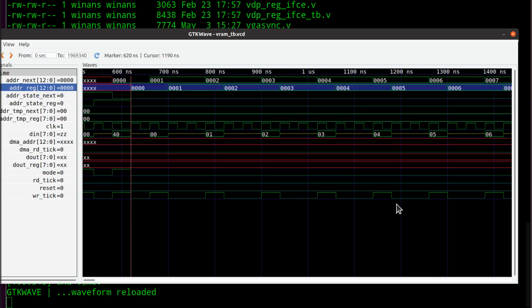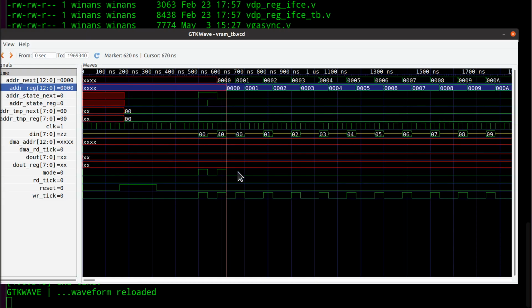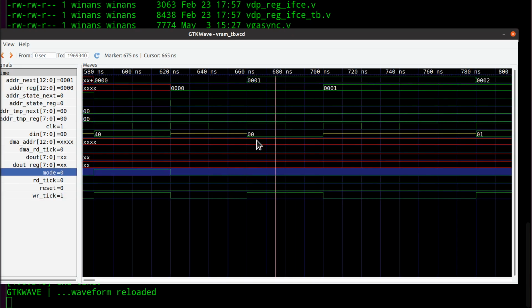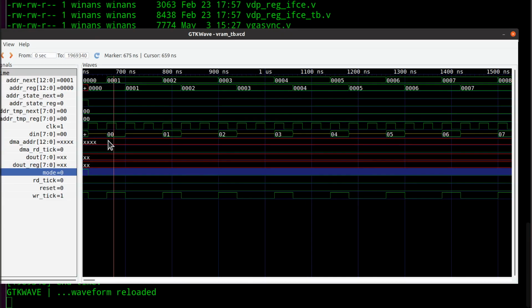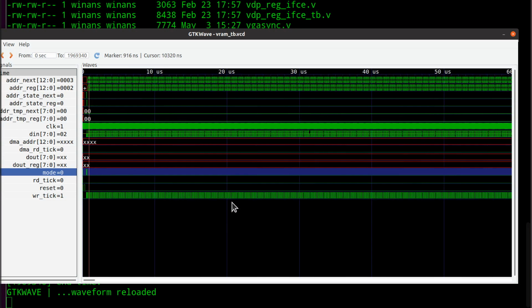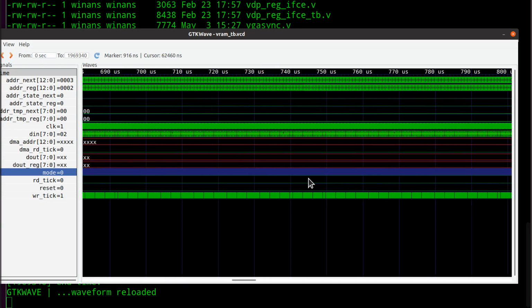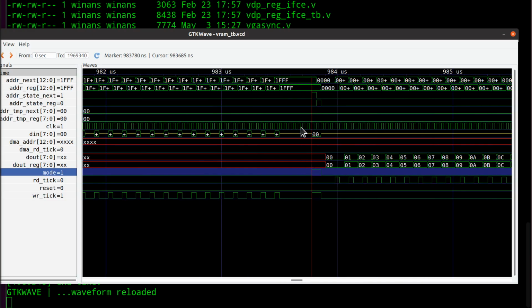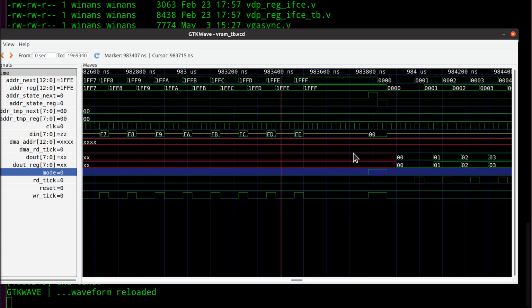So anyway, we've got subsequent write cycles going in here. It's all set up. The counter is going to count. That's why you see it going 0, 1, 2, 3 here. Every time there's a mode 0 write of whatever this is, a 0, into the current address counter value, which is 0, you see right here. And then we write a 1 into the address of 1 and a 2 and all this other fun stuff. So it fills it all up until over here, and you'll see it stop 1 early. Whoa. 1 early because it's going to stop at 1FFF, or FFE rather.